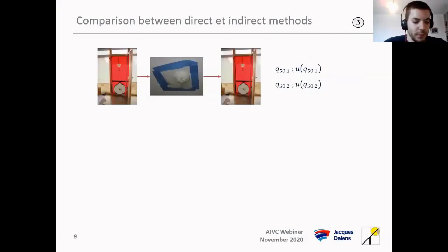Then the third repeatability study, which was used to compare direct and indirect methods. I will not go deeply into the indirect method since Vitor told us about it, but simply it's two fan pressurization tests and the sealing of the component between them.